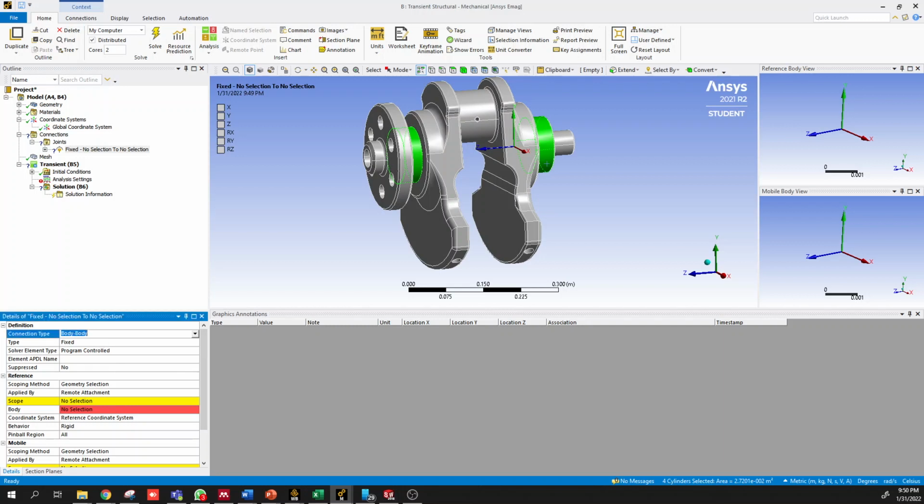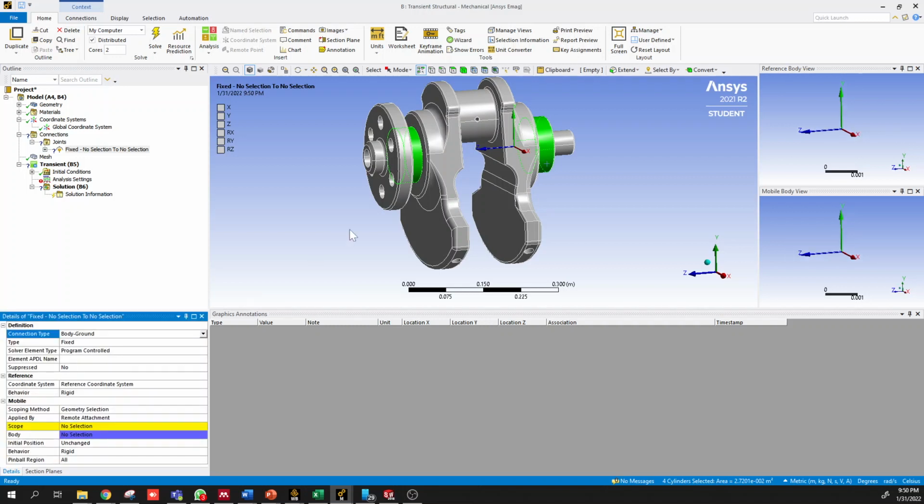because we have a connector, we need to define a few things. The crankshaft is going to be the other side of this connector. Think of it kind of like a spring that you can define stiffness. So instead of between two bodies, we only have the crankshaft here. If we had the crankshaft and the connecting rod, we can say that this connector is between two bodies, but we're actually between body and ground, because we can assume that the engine block is just something that is, for all intents and purposes of this simulation, rigid.